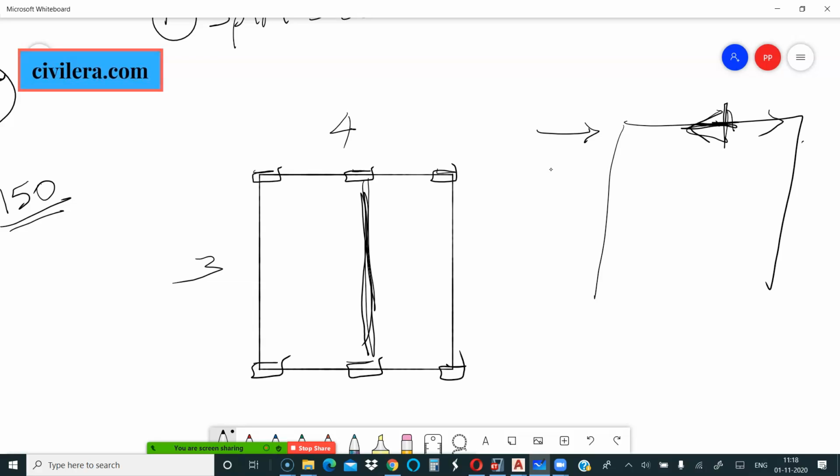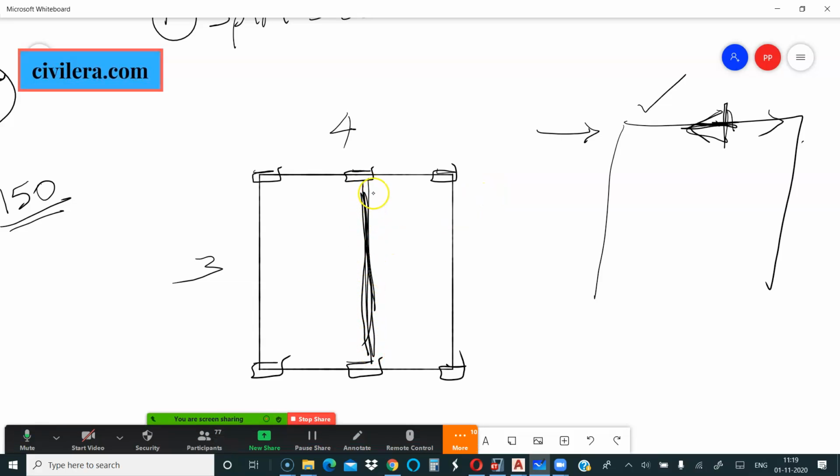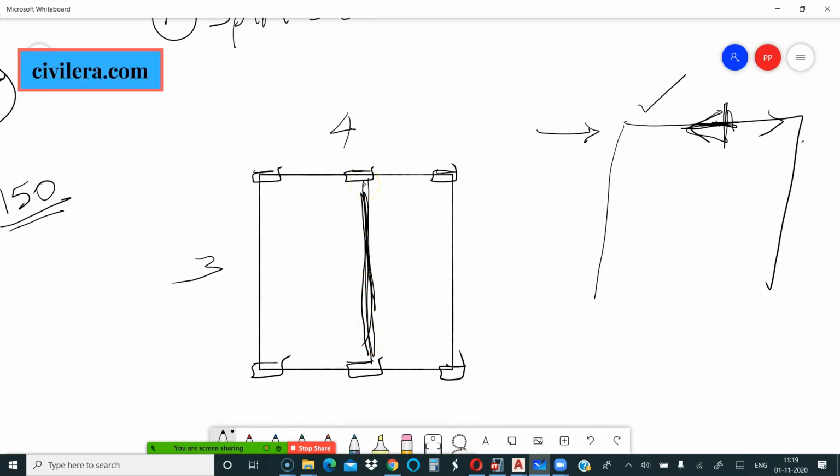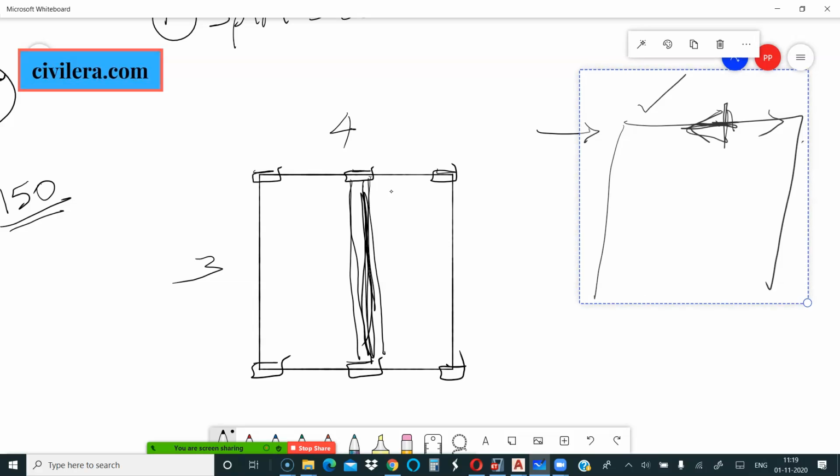So these are behaviors that we want in the building. So we will have to tie all the columns by a beam. So that's the second requirement. In case the client has an objection to having a beam here and asks you to avoid that, maybe you can give a concealed beam here, a wide concealed beam with top and bottom steel running through the beam or the slab.